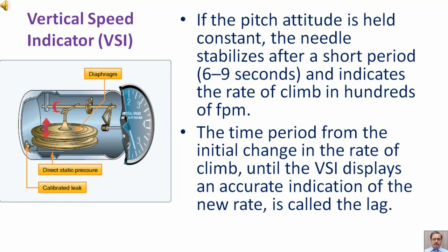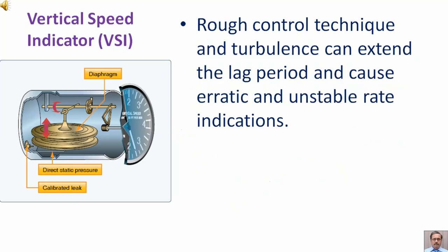The time period from the initial change in the rate of climb until the VSI displays an accurate indication of the new rate is called the lag. Rough control technique and turbulence can extend the lag period and cause erratic and unstable rate indications.